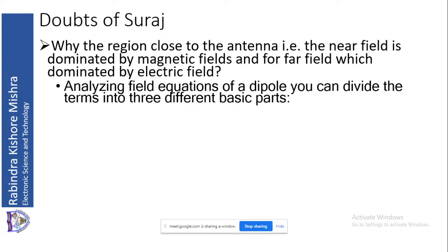In that case, you just integrate the Hertzian dipole results over the length of the linear antenna or any other antenna. So any antenna can be decomposed to its basic form; the basic building block of any antenna is the Hertzian dipole. Similarly, if you take a loop antenna, it is again a Hertzian dipole, but in the magnetic sense, while this is a Hertzian dipole in the electric sense. That loop will be equivalent to a Hertzian dipole in the magnetic sense.